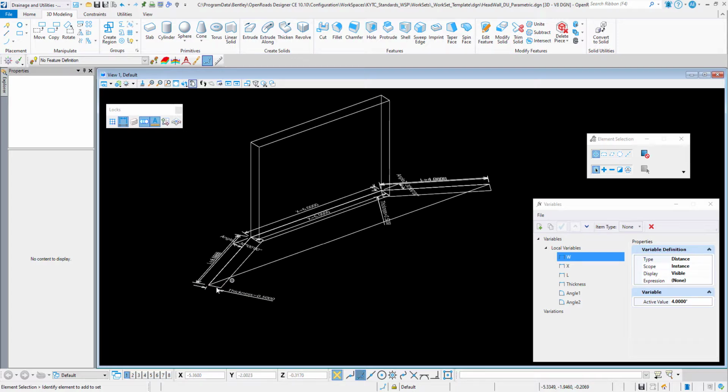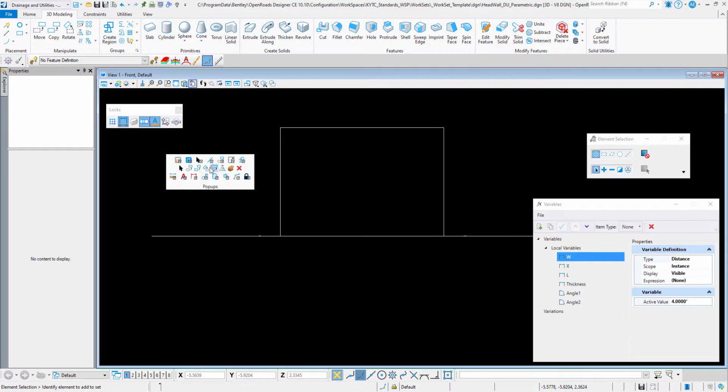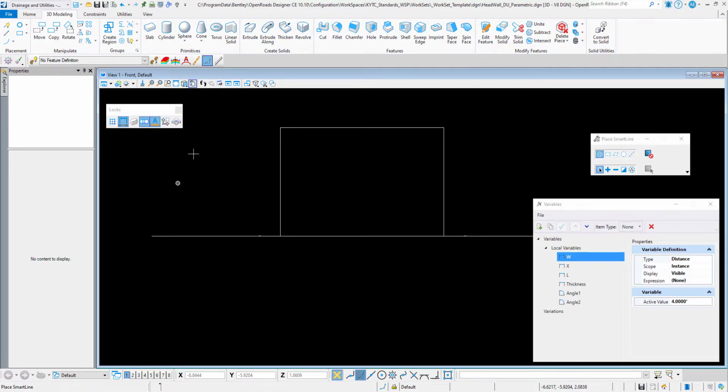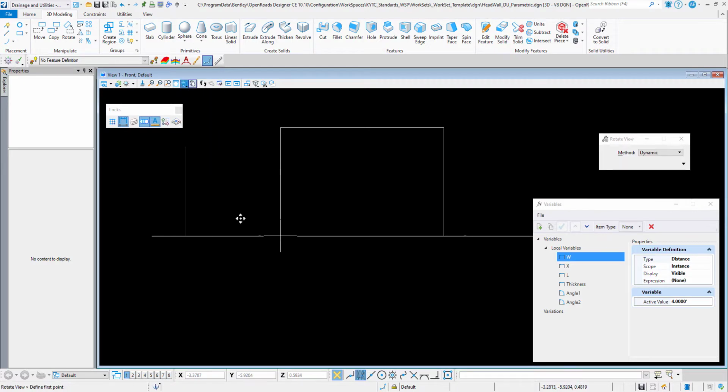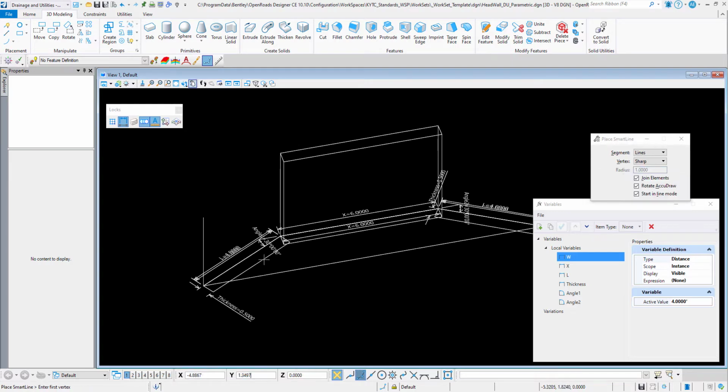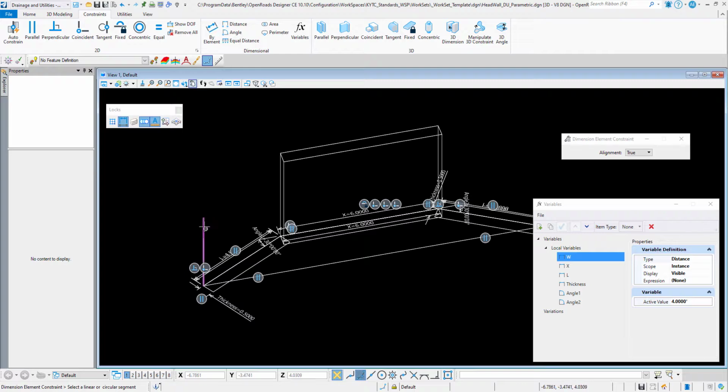And the next step is I'm going to start drawing my wings. And so what I like to do is I like to draw, again, helper lines. I move to my front or my right view, and I'm using AccuDraw to lock in a completely vertical line here. And this is going to be a helper line that I'm going to use to place at the points that I want to make sure I draw along the same plane.